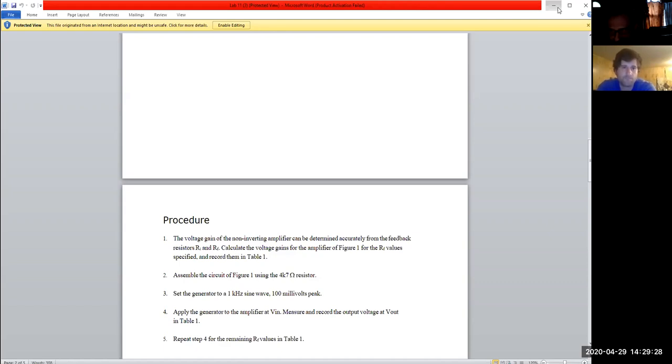Because you want the filtering in the very beginning, so when you're converting your signal, it puts the least amount of stress on your other stuff, right? So the really expensive power supplies, that whole input section is usually packed, because they want to make sure the signal they're getting in is super clean and not going to short anything out. Especially the industrial ones, where you're more susceptible to getting ground bounce and all that.